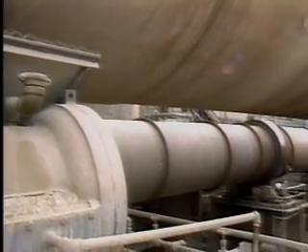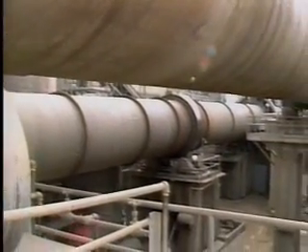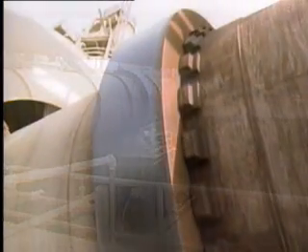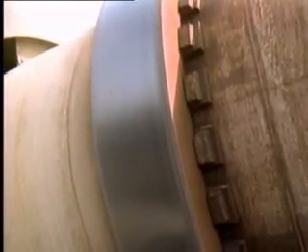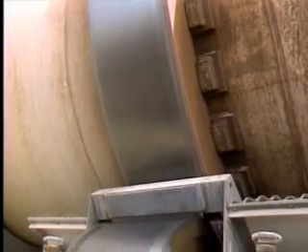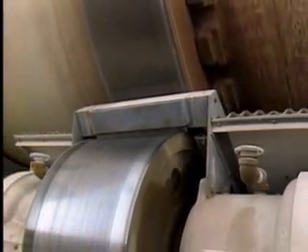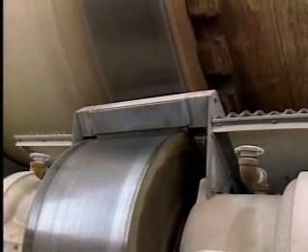The rollers support a large rotating kiln. The high kiln temperature makes the rollers hot. This heat and the kiln's weight would quickly melt and wipe away ordinary grease. This graphite lubricant is in the form of a solid block. Because it's a solid, there's no danger of its melting away and leaving the metal surfaces unprotected.